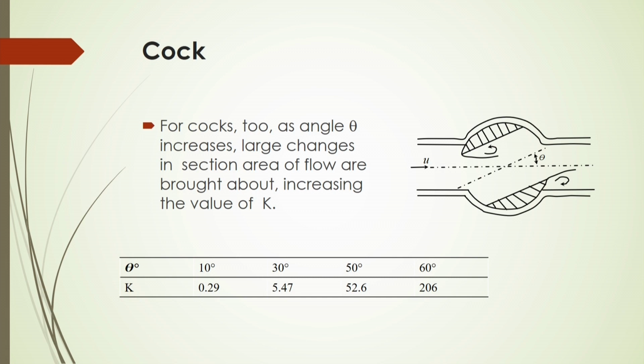Now, similarly for cocks, as shown in the figure here, as the angle theta increases, large changes in the section area of the flow are brought about, increasing the value of K. So, if we increase theta, the respective values of K are shown in the table here accordingly. You can consider what the minor loss coefficient should be for a cock.